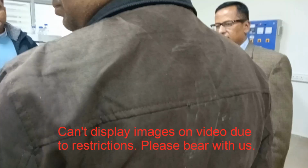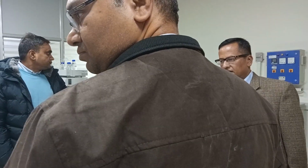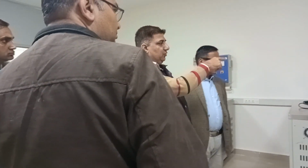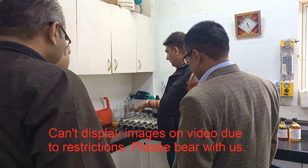And this is for the PMA analysis. This setup is for the PMA analysis. And this is for the deflection of the oil, we can measure this one. And this is for the corrosive sulfur. This is the aging oven for the CRGO samples. This is a general oven for glassware and other things. These are the special bottles for the collection of oil samples.